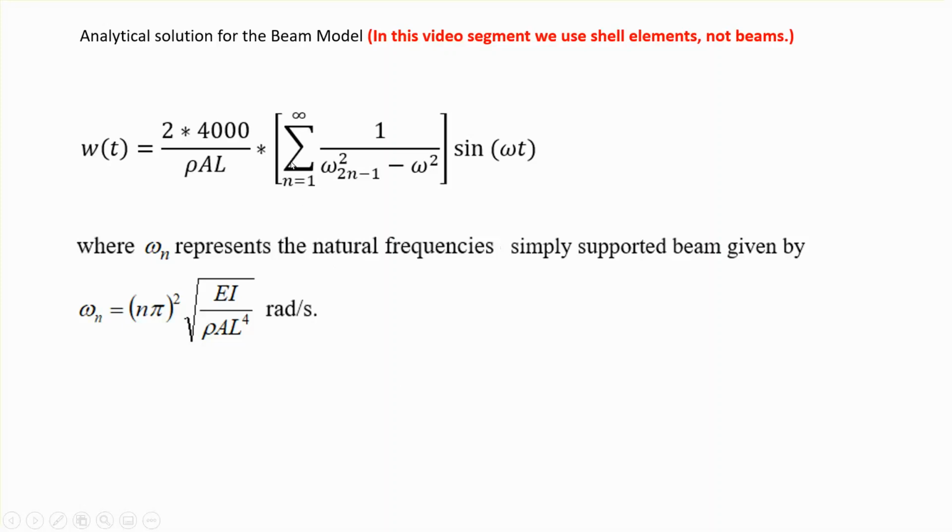However, I want to point out that if this problem is viewed as a beam problem, there is an analytical solution. The analytical solution, which is the vertical displacement of the midpoint of that simply supported beam, is given by that expression. Notice that this thing is all a constant. And there are an infinite number of frequencies. They're all calculated like that.